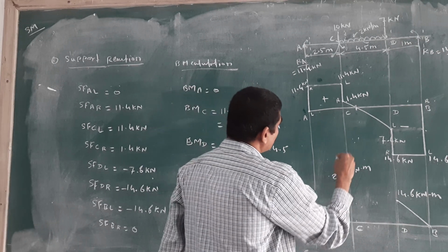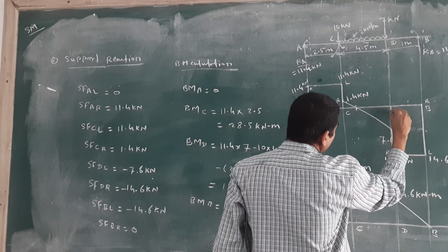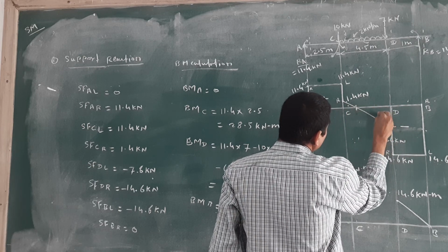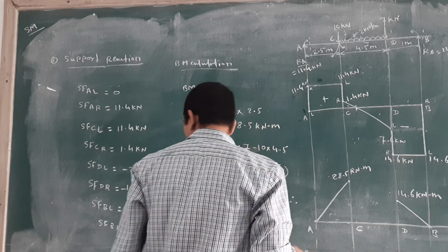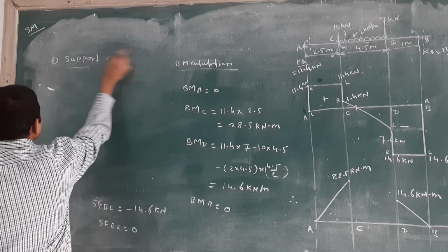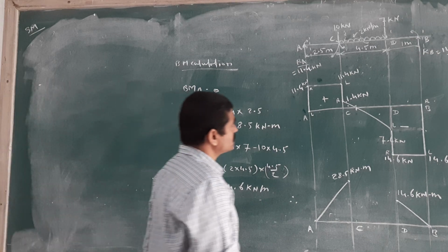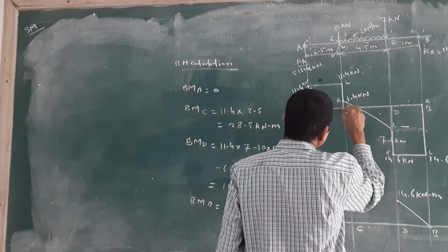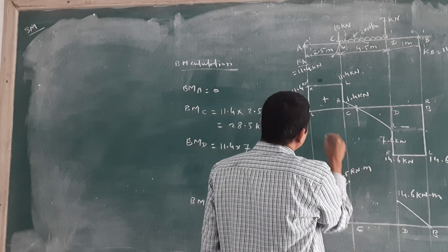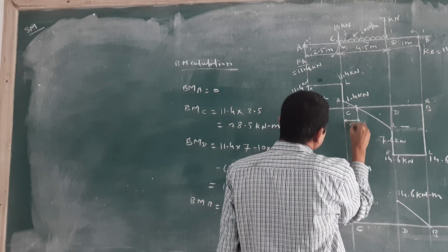See, if you are getting a triangle here, the C point to the D point, we'll consider only this, C to D. Here we'll get one triangle and here we'll get another triangle. You have seen in mathematics how to find out the distance. We don't know where the shear force is 0. We know this distance is 2.5 only. We will consider this distance A.